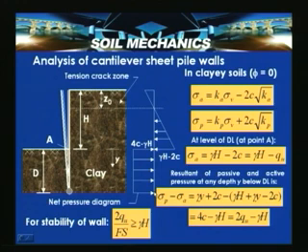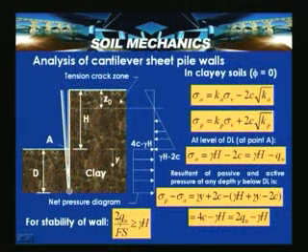So in the analysis of cantilever sheet pile walls in clayey soils, we are using the fundamentals that we discussed and applying the relevant earth pressure coefficients. If it is layered soils, then we need to apply the relevant coefficients, and we can calculate the earth pressures and arrive at the net pressure diagrams, and then calculate the required features and check whether the required depth is adequate or not. As a thumb rule, for the stability of the wall, if you are able to maintain 2q_u/FS greater than or equal to gamma h, then you can say that the wall is stable.